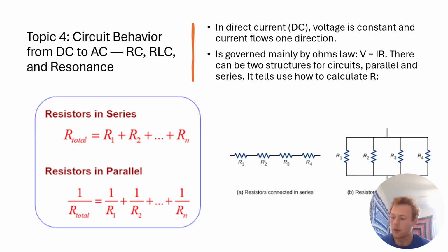And the surrounding water has a resistance of 800 ohms. And it's asking us about the current. Most of these DC problems simplify to just manipulating V equals IR in some way. And so here it's just I equals V over R. We need to find the V net of our problem and our R total.